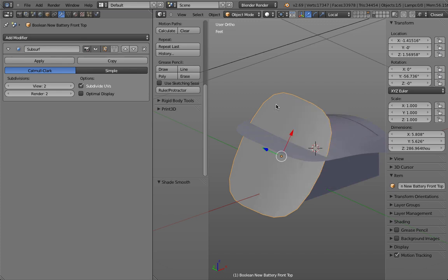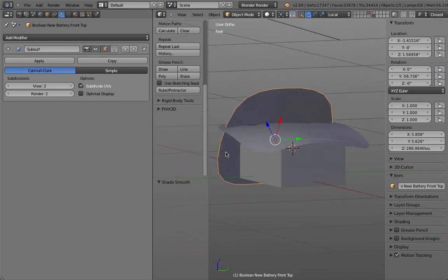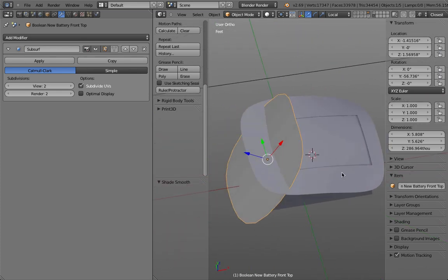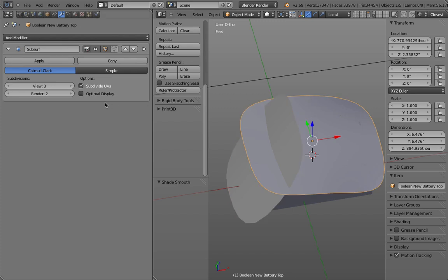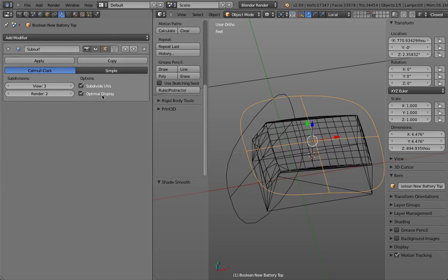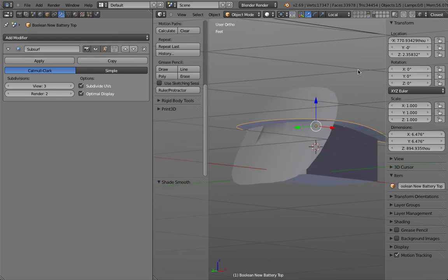You might notice that right now it's a little bit difficult to judge your form model because you always have those meshes there. So 2 tricks to clean this up. First, with all these meshes in their modifier for subsurface, we turn on optimal display. Optimal display simplifies the mesh preview.